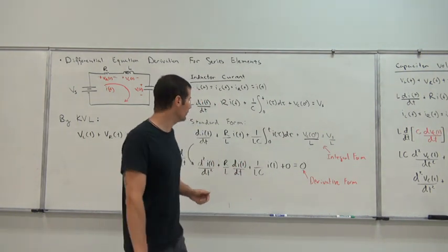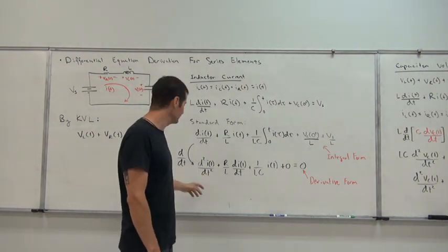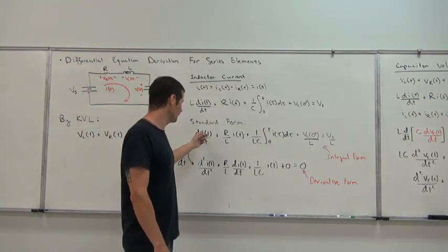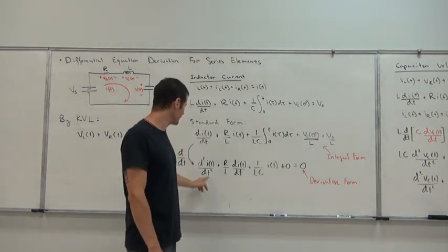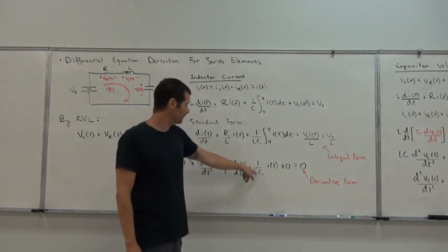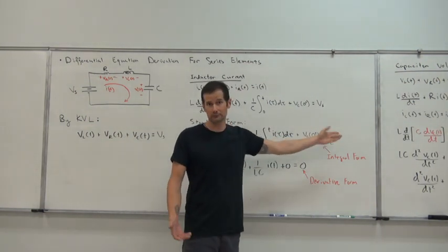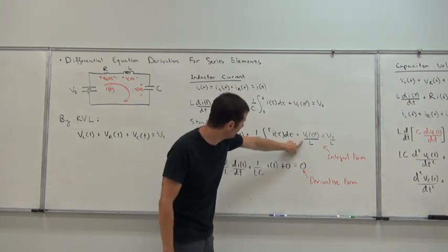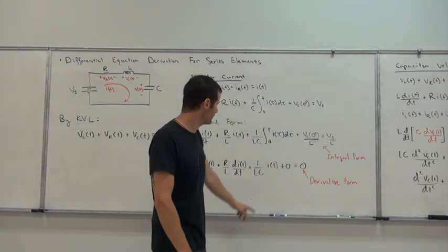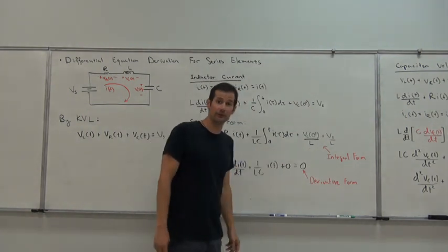We can easily go ahead and put the integral form into its derivative form simply by taking its derivative. Now, we take its derivative: the first order differential becomes a second order derivative, R over L times di_t/dt plus 1 over C times i_t. In this term, this would be the initial condition, and that would be the voltage source divided by L. The derivative of the constants is 0, so both of these go to 0.